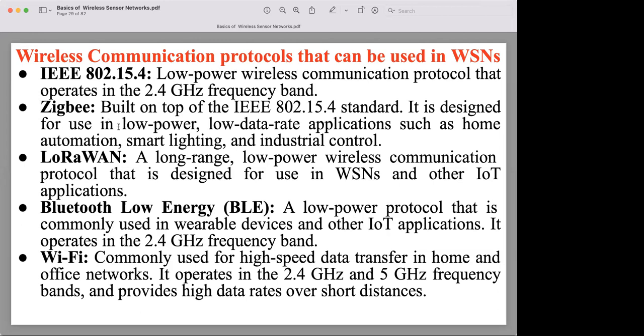For long range communication, we can go to other wireless protocols such as 4G, 5G. Short range communication protocols are good in terms of energy consumption. Long range communication is good in terms of communication distance. But long range protocols consume huge energy, while short range ones have communication limitations. So LoRaWAN comes into the picture. LoRaWAN consumes very little power, less than or equal to Bluetooth, and the communication range is some kilometers, 5 or 10 kilometers. So they cover the disadvantages of both short range and long range protocols. Right now, various devices use LoRaWAN for such applications. And we will see these protocols in detail next.